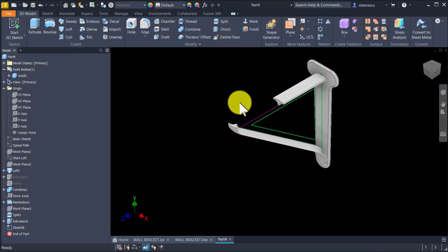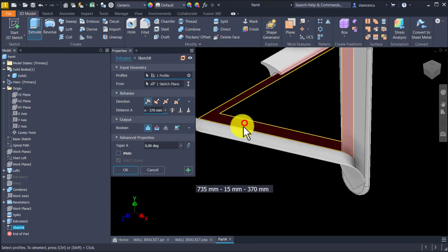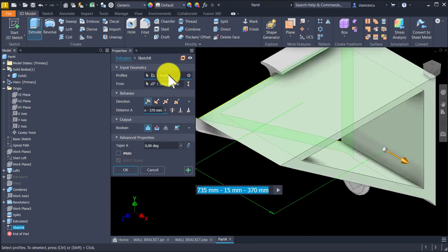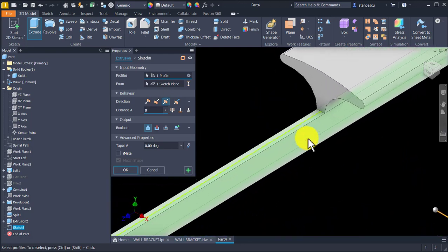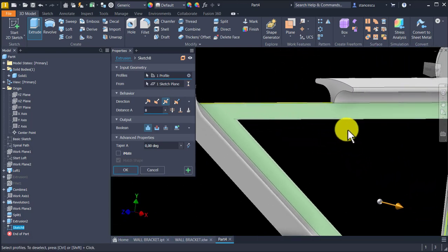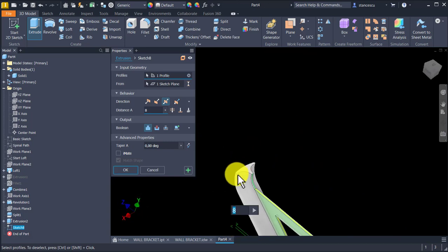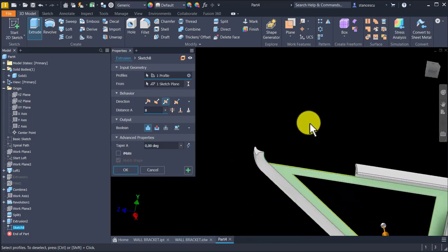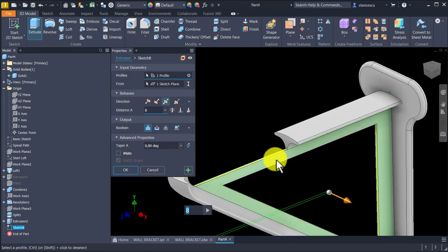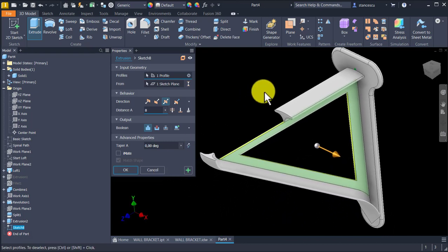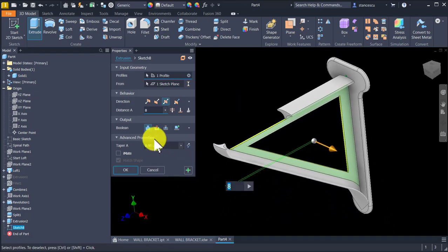Finish sketch, extrude, 8, my friends, 8 millimeters and symmetrical. Yes, you see here a contact. Yes, we have an end here, and other new features will be connected with this. Yes, this is okay. Join.